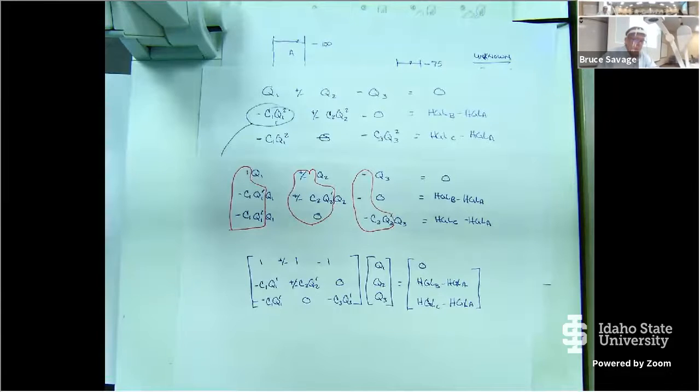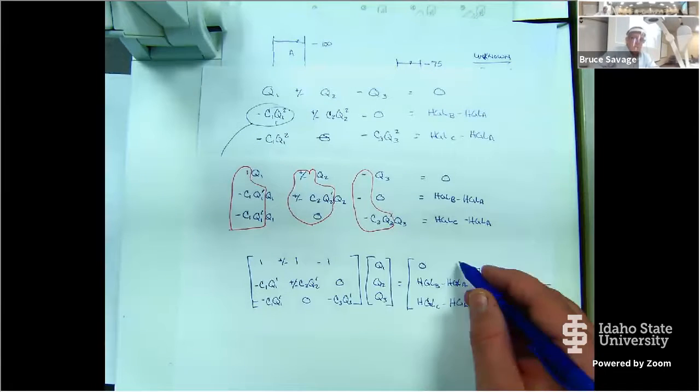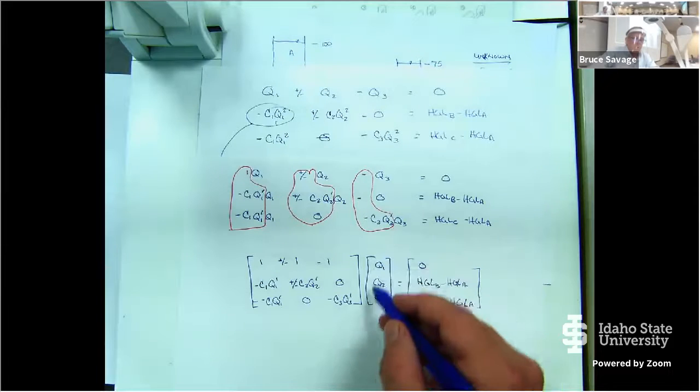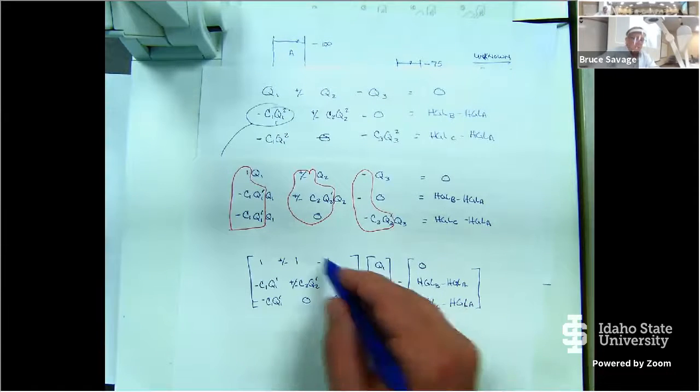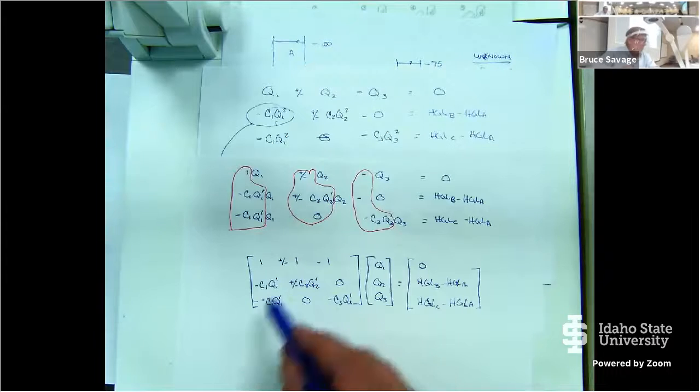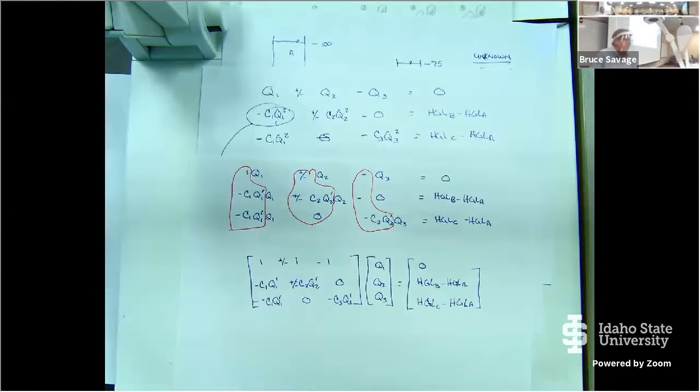So now that we have that and everything looks good like it's in matrix form, because we know the hydraulic grade lines at our reservoirs, we know we're looking for the 3 flow rates, and we have our coefficient matrix, we know the C values, but we still have this pesky plus or minus term, right?